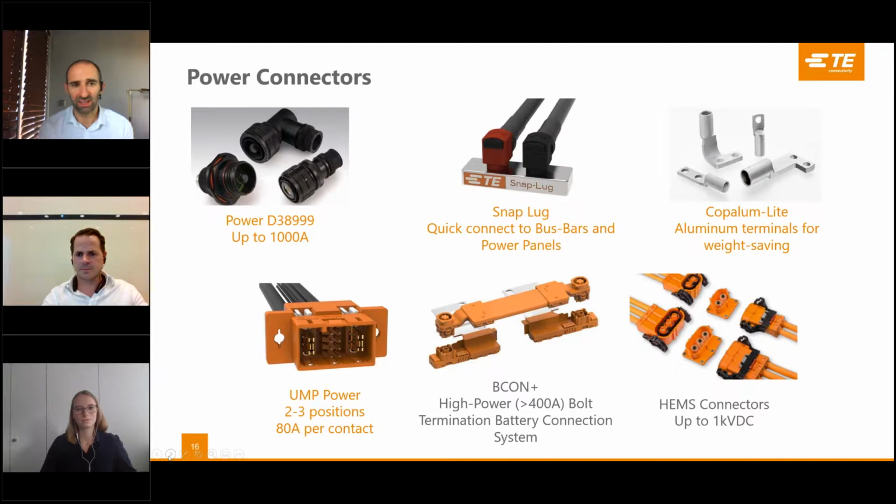Power connectors, obviously very important for this application of eVTOL. And we have, again, a lot of experience with high current connectors, the 38999 standard of connectors. We have some innovative products like SnapLug and other busbar type connectors. A lot of our customers are using Copperlite, which is an aluminium style connector, which is very important, again, for saving weight.